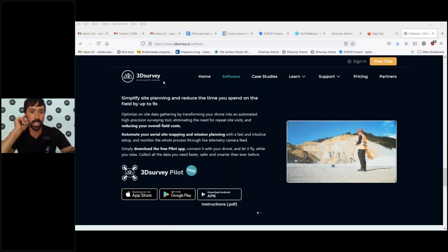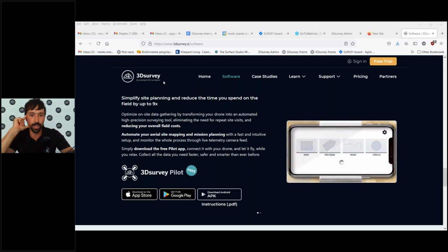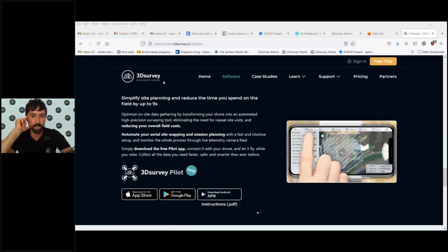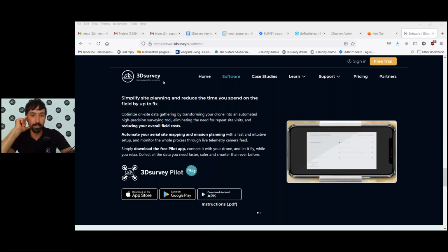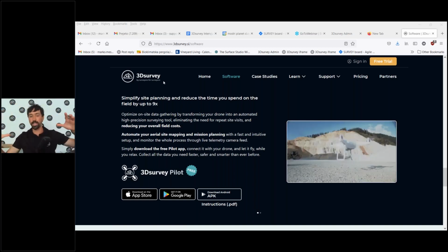Another question: can we do large area mapping with nadir images from a drone as well as a normal handheld full frame sensor camera, mainly for catastrophe measurements? Yes, you can, but you need to connect those 2 models with some kind of side images.